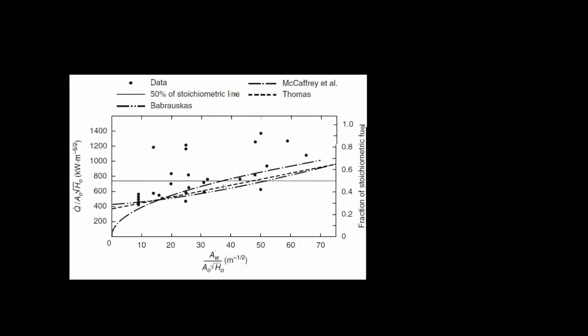So going back, once you understand this principle, you can understand Philip Thomas's equations, that value, Q sub F naught, that value is your threshold for flashover. And we have the capability to evaluate that through your mass flow rate. What I wanted to emphasize by this graph was just the dependency we have on accuracy of our data.